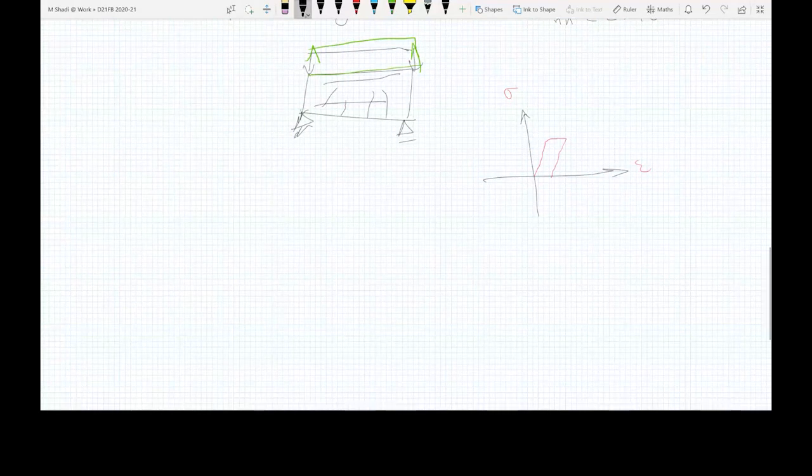Now, this is going to move in a completely opposite direction. So this is going to move downward, the stresses are negative, and the deformations are pushing back in the opposite direction. The strains are going to get into negative strains at some point, and it's going to yield in compression. You'll get large strains, and then probably cracks happening at the top. And then you relieve that, it's going to go back, but it's not going back to zero strains. There will still be some residual strain, but on the negative side.